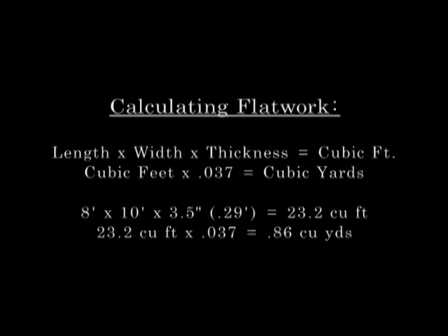We'll also lay out how to calculate how much concrete you want in the following chapters. We use basic math to come up with the calculations for estimating your concrete. If you take the length and width and thickness of a slab, for example, in feet, and multiply that out, that'll give you the amount of concrete in cubic feet.